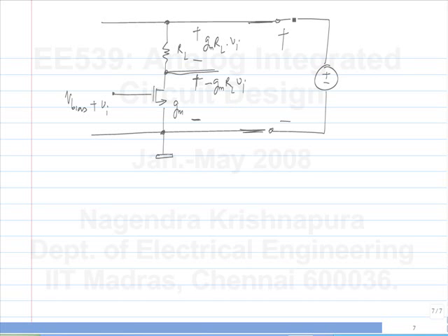Now, first of all, the source will have some impedance, which typically is some resistance and an inductance. And the line that is connecting to this circuit will also have some impedance. So the incremental current that is flowing through RL will also flow through all of this. So the actual voltage you see here between the drain node and ground will be minus GMRL Vi plus the drops across these impedances as well. So if you feed it to the following amplifier, you will get not only Vi but something else. Now in this particular case, this current is dependent only on Vi, but that's not always true.